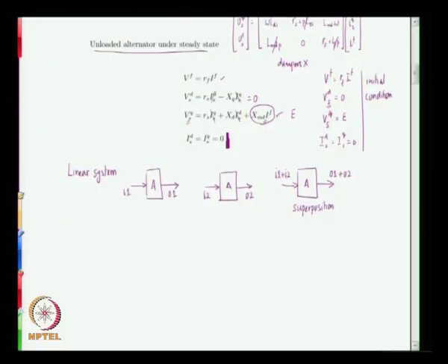How do we use that? Now if you have the alternator operating on open circuit, let us say that you have the d axis of the alternator, we have seen an equivalent circuit for the d axis. So let us just represent that equivalent circuit by a box, and you have two terminals of the equivalent circuit for the stator representing the stator.